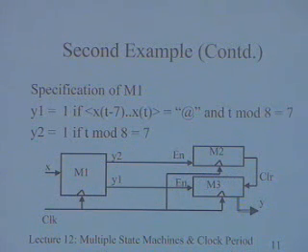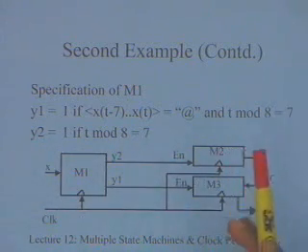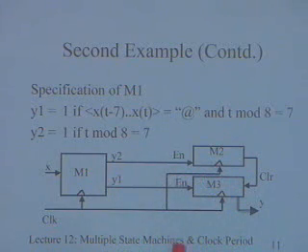So when you look at any type of design, you might have to look at not designing just one state machine, but designing more than one state machine with very clean interfaces. You should have a very clean specification of the interfaces and not do the design arbitrarily, because the partitioning may be more by experience and ad hoc, but the interfaces have to be very clean.